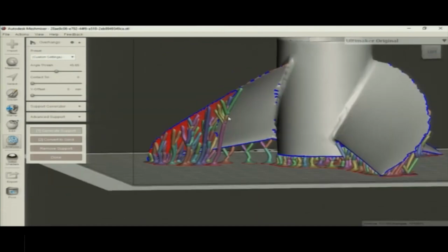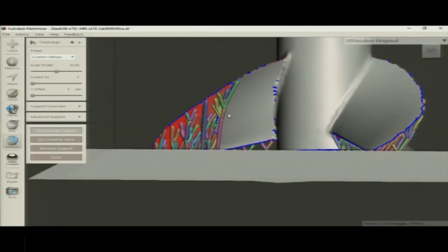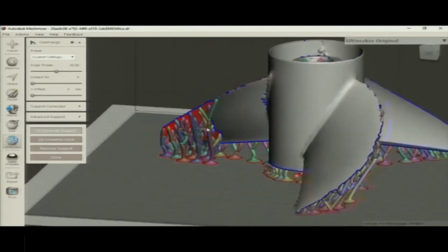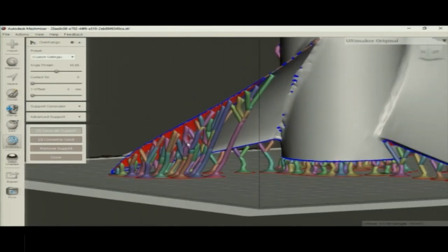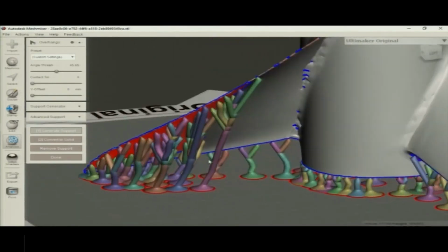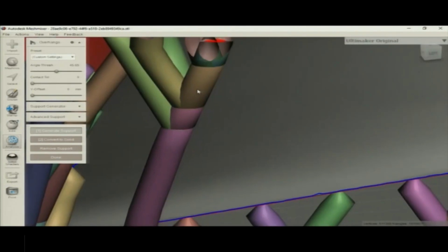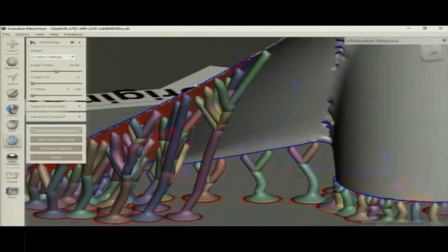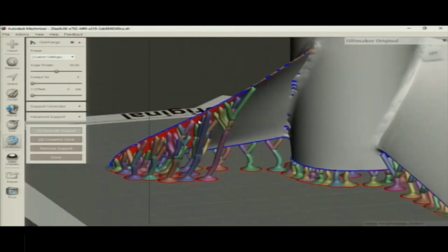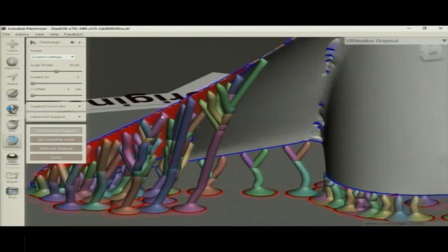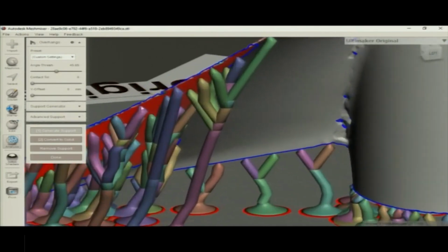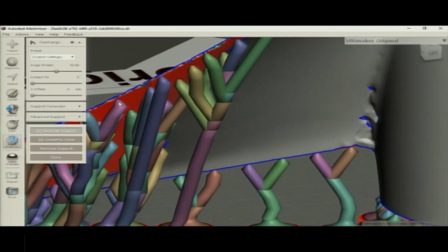You can see here, advantage of using Meshmixer is that we can provide ergonomic support structure to our 3D printed file. One of the issues that is to be considered here, the supports are very easily removable here.